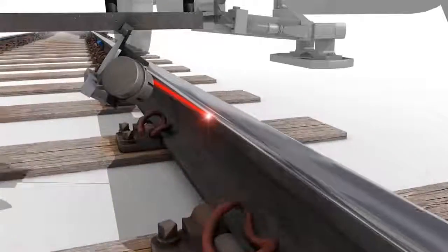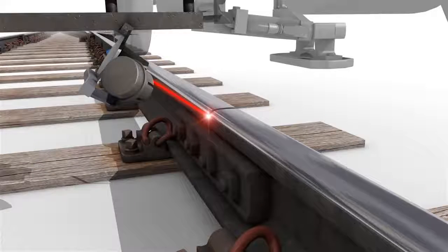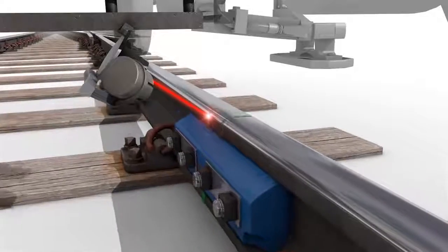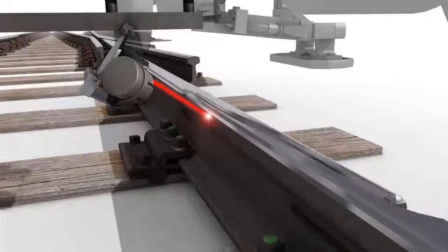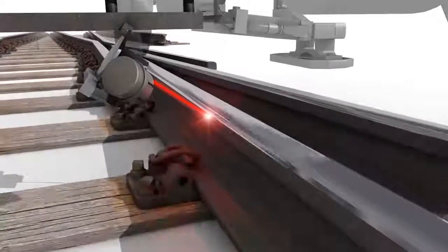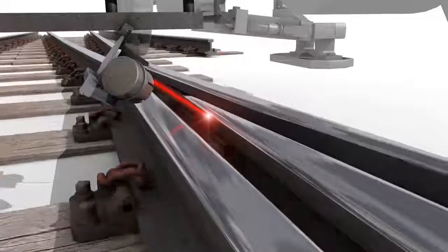Instead of measuring 14 mm below the crown on the gauge face, it measures across a gap in the rail, causing a gauge spike. For example, a joint, IRJ, adjustment switch, or a crossing nose. Incidences of a no-fault found defect need to be reported to the section manager for further investigation and recorded on the fault report.